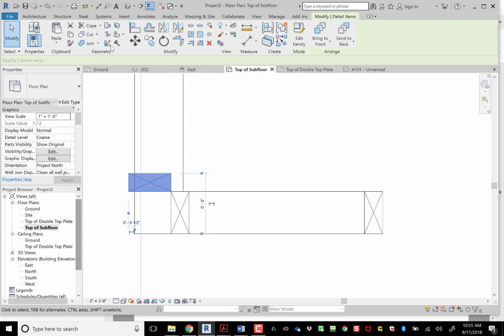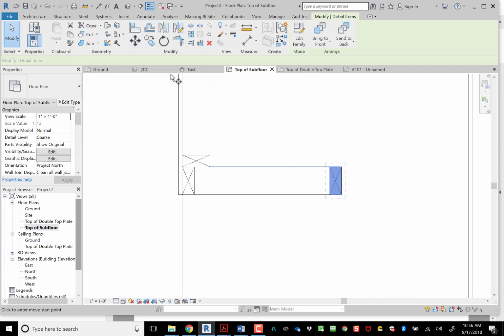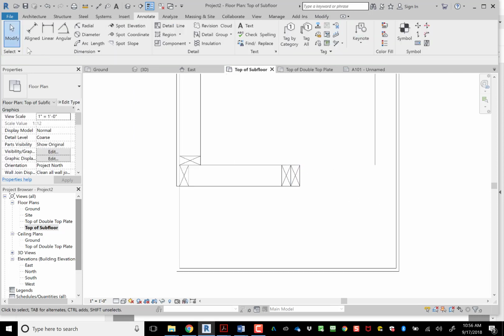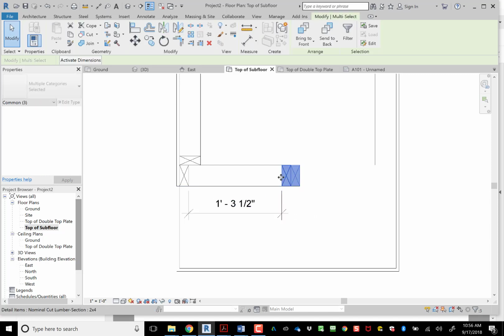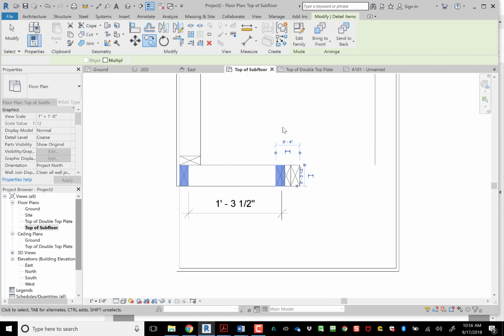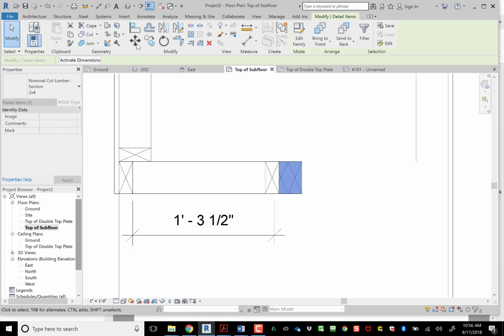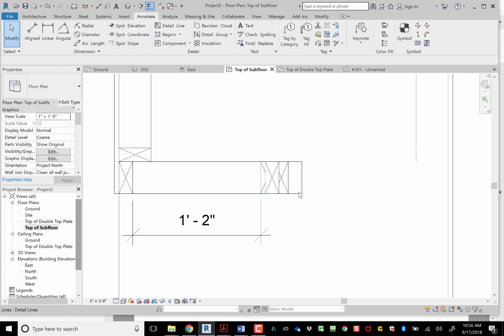Okay? So this is where you need to kind of work on your design. This one might go here. Okay, and then I know that this is an opening, potentially with a header, with a king stud and a trimmer, so maybe you need 2. And then if I do the dimension between these two, it's just a little bit over 16 inches. So maybe I want to move this 16 inches on center, and maybe I want to just change my design. So I move this over. Does that make sense? Because then you just saved a whole stud, right?